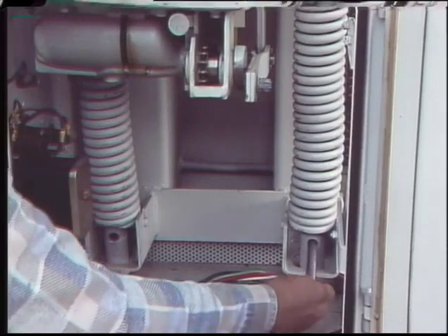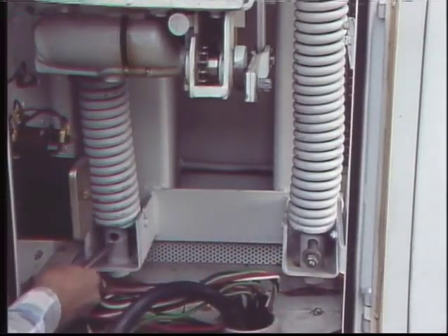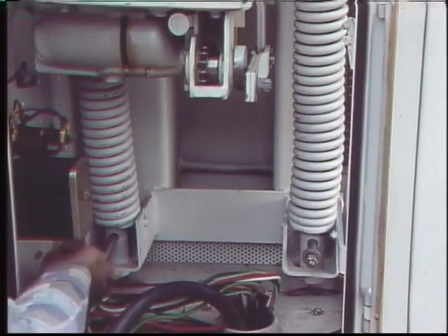Isolating a breaker from its operating mechanism prevents the breaker from accidentally closing or tripping while it's being worked on. The purpose is to keep the workers from being injured. The way a breaker is isolated from its operating mechanism depends on the kind of operating mechanism it has. For example, the closing springs on a motor spring mechanism are physically blocked to keep them from operating the breaker.